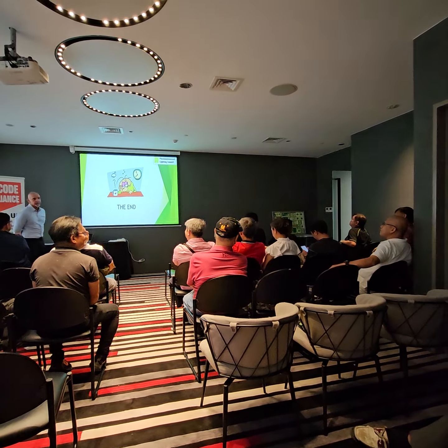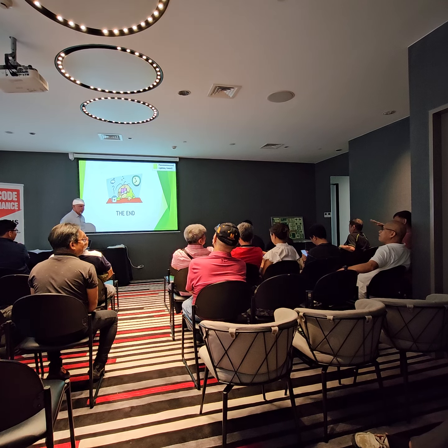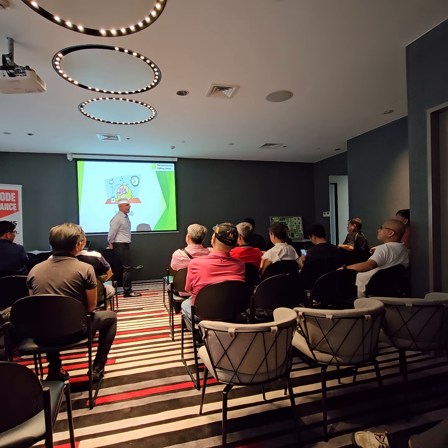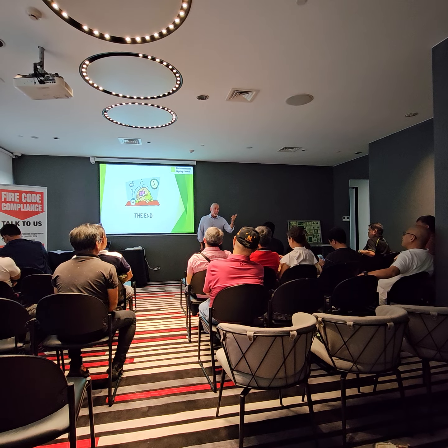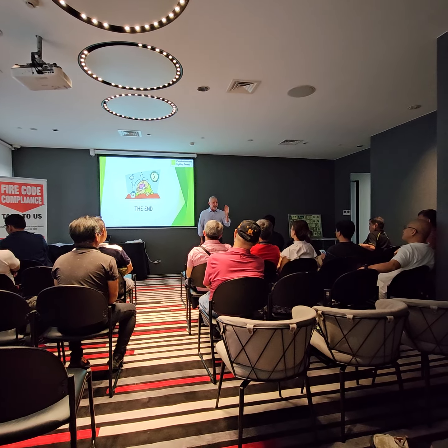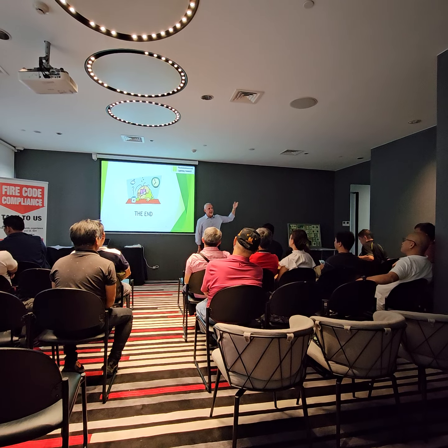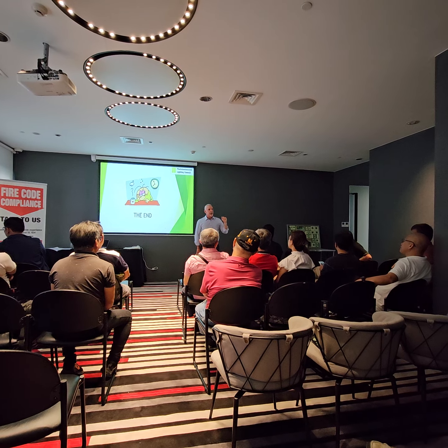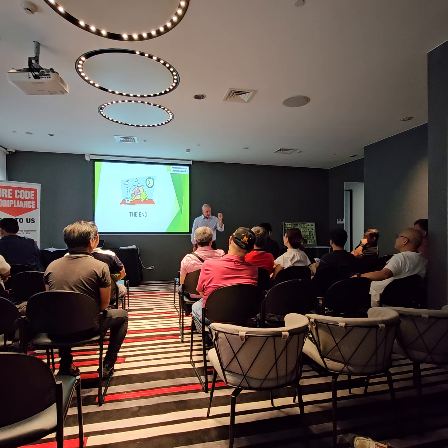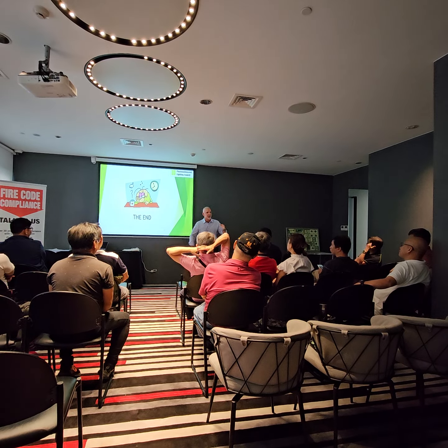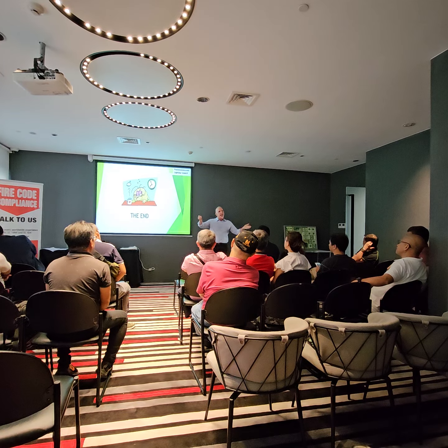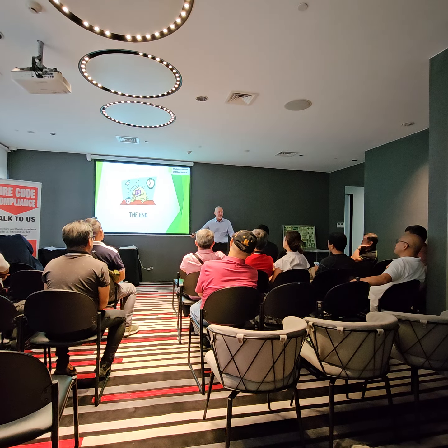That 54 lux, is that the standard? Yeah, that's UL 1994 and UL 924, all specified in the test method. 54 lux for 60 minutes. So that's to charge a photoluminescent system. It's not saying you need 54 lux of emergency lighting.